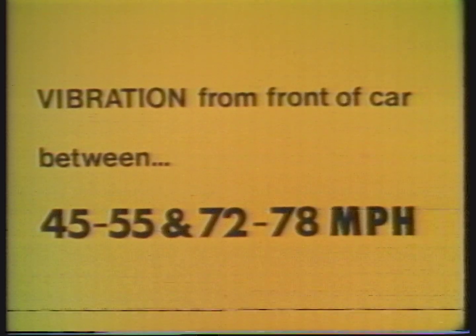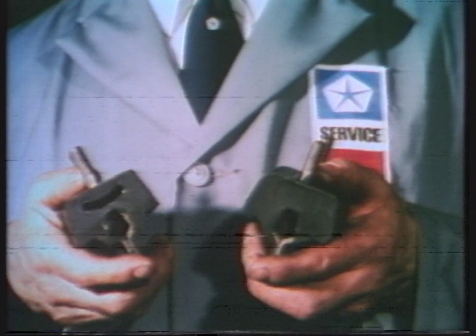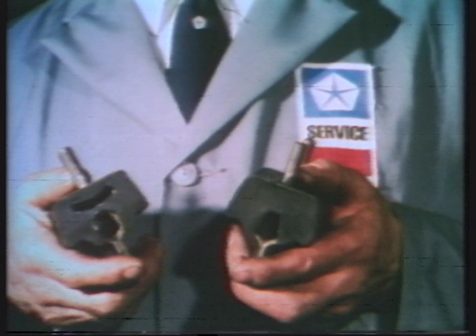suspension frequencies. So the next step is to visually check engine mounting rubbers for condition and check that correct type mountings are fitted at each side. If on road test vibration was identified to the engine, slacken the engine mountings and exhaust hanger brackets. Run engine up to the RPM at which vibration was noted, allowing the engine and exhaust system to self-align themselves.